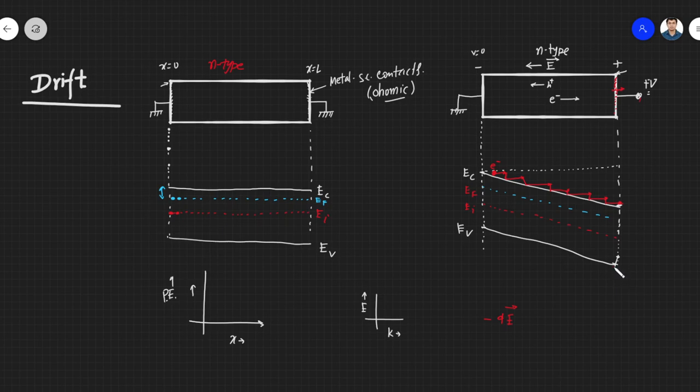So you can assume that holes are kind of bubbles under the water, right? So they tend to move upwards, and for electrons it's easy to move downwards. For holes, it is always easy to move upwards, because for holes the potential energy increases in this direction, and as it goes up for holes, the potential energy decreases, right? So what happens for the holes? They also follow a similar pattern like electrons, keep moving, and then collision happens, and this process goes on.